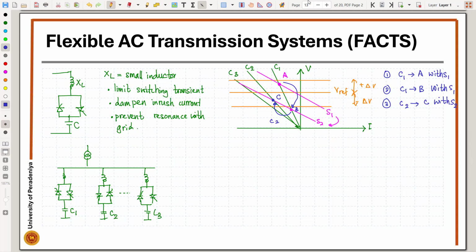Yes, sir. They normally use a power factor regulator with predefined steps. Yeah, so that's the thing. So we have a manual switch. So here with the thyristors, we can automate it.